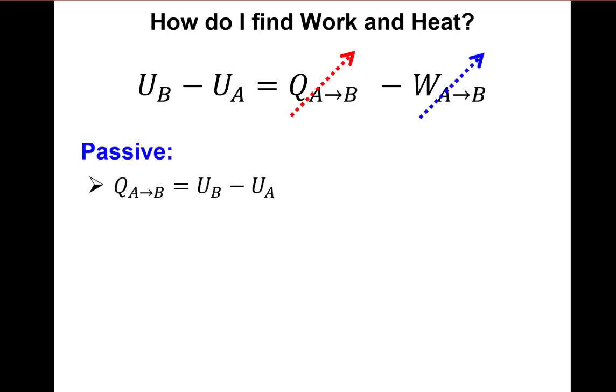So at least in this particular cycle, the Otto cycle we'll talk about today, we'll assume that all the processes are either isochoric, that's really when we're interested in the heat transfer, or that they're adiabatic, when we're interested in the work. So really, you can see from this, I've got to fix all the states, right? And if I can fix all the states and I look at each individual process, I can find either the work or the heat from delta U, delta big U, right? So that's m times the change in the specific internal energy.